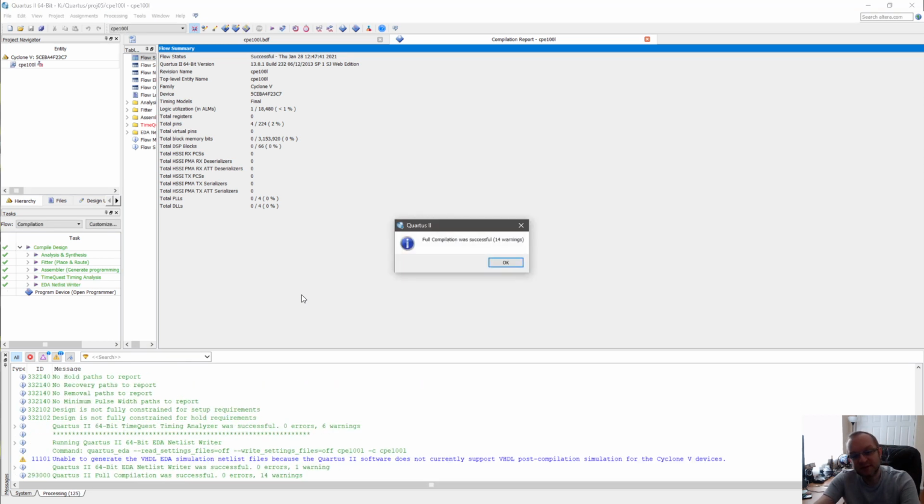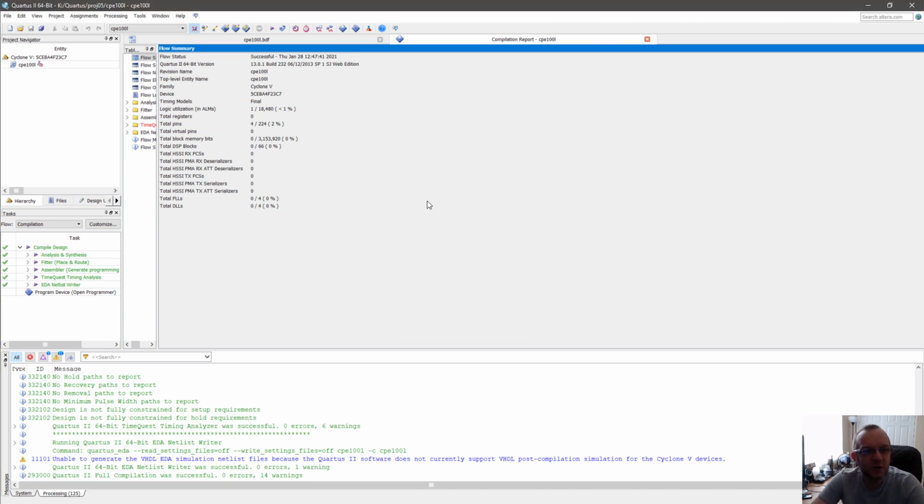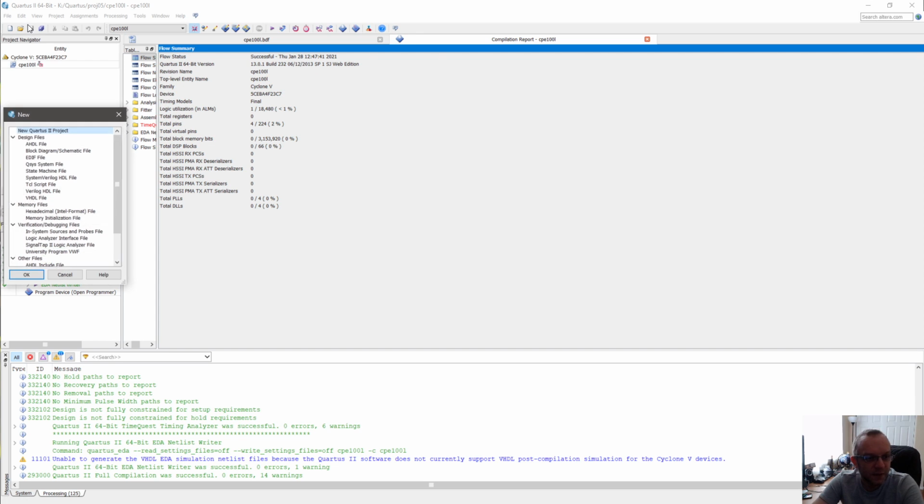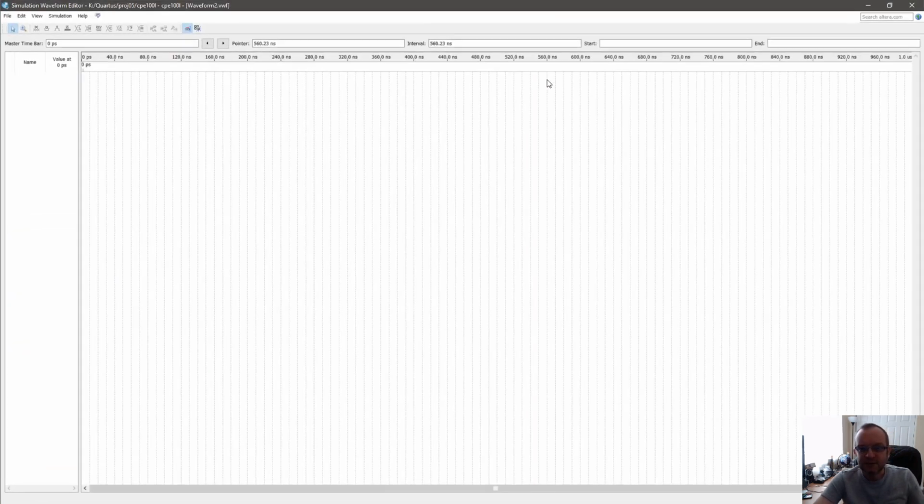Every time you modify the circuit, you have to recompile before you attempt the simulation again. Okay, so I got the message, full compilation was successful, 14 warnings, that's okay. So now I'm ready to add a simulation component. I go to File, New, and from this list you need to choose University Program VWF. Okay, and you will get this window.